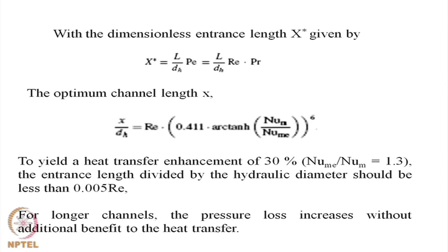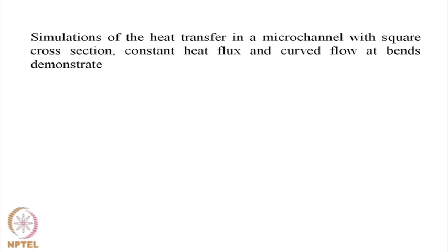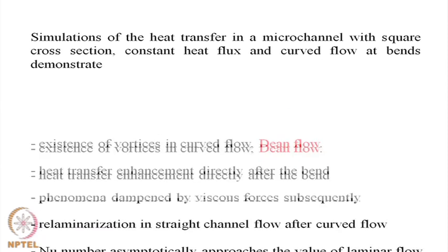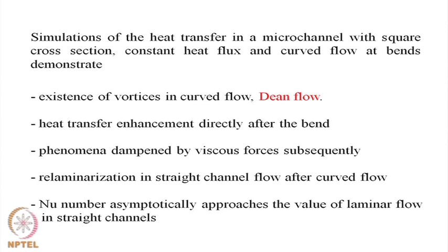But there is obviously a limit to this. If you use a longer channel, then the pressure loss increases without any additional benefit to heat transfer. So, regarding simulation of heat transfer in a microchannel with constant heat flux and with curved flow at bends, they demonstrate certain interesting trends which we have already discussed, but I am summarizing it here.